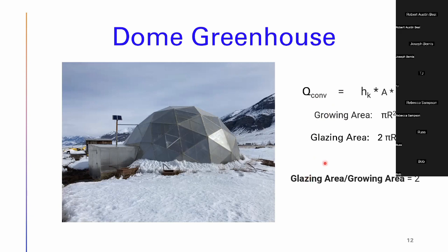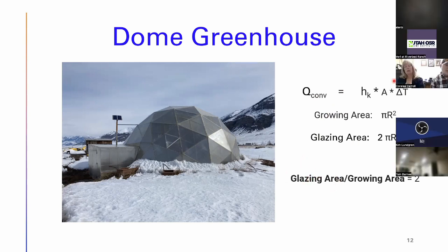This is the other factor in designing your optimal greenhouse. It's glazing area, so your polycarbonate, so that's the area here. That's the area that's affected by the temperature differential. The differential being defined as the temperature outside your greenhouse minus the temperature inside your greenhouse.